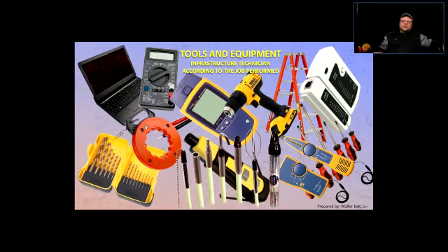All right, so you push that into raceways such as conduit, EMT, and you just keep pushing until it comes out on the other side, wherever the other end is. And on that end, when it comes out, you can do two things. You can tie a wire that you're going to pull through, and you just keep pulling it, and you get the wire in the pipe, right? Or you can tie a string, just a regular twine string, like a rope.